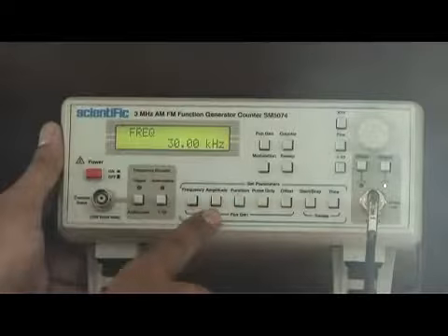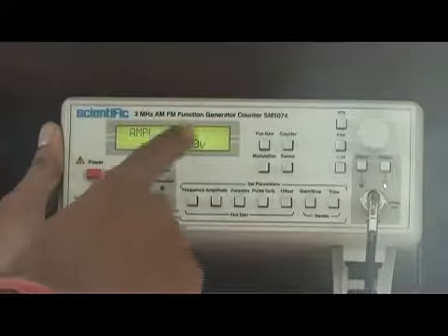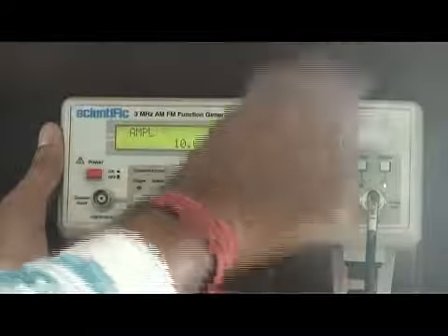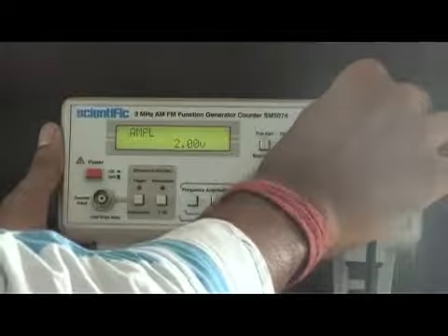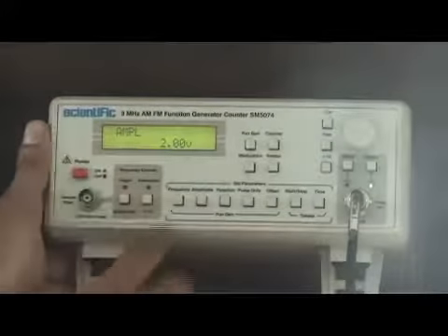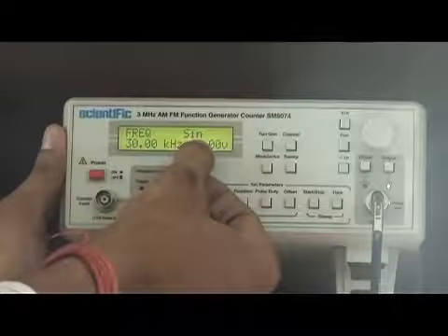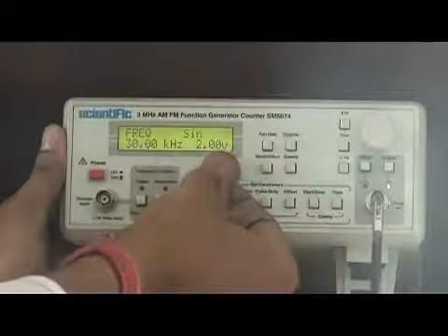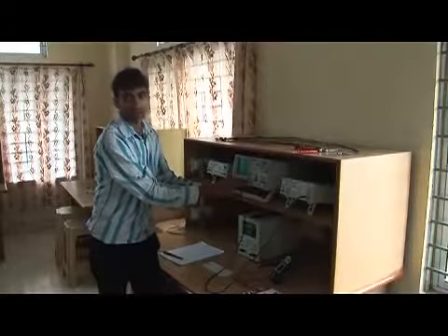And next there is one more button called amplitude. Now you can see it's AMPL, denoting amplitude, and right now it's generating an amplitude of 10 volt. Using the same knob you can vary the amplitude. See, it's varying. So suppose we are using an amplitude of 2 volts. So right now I am generating a sinusoidal wave. It's SIN, called sinusoidal. Frequency is 30 kHz and amplitude is 2.004. So whatever is being generated here, let's see whether that is being received here or not.